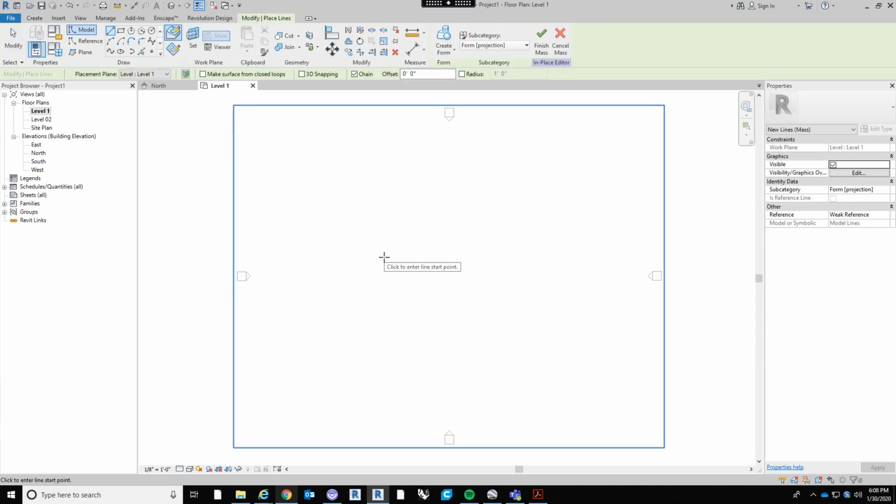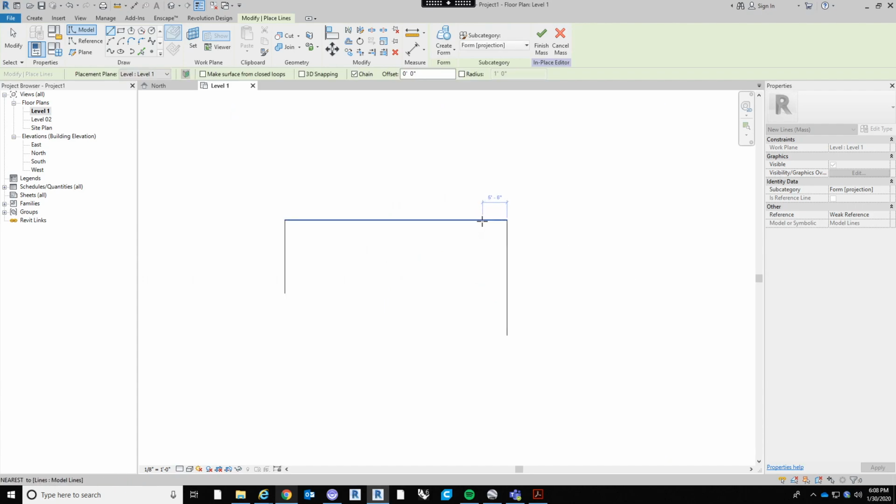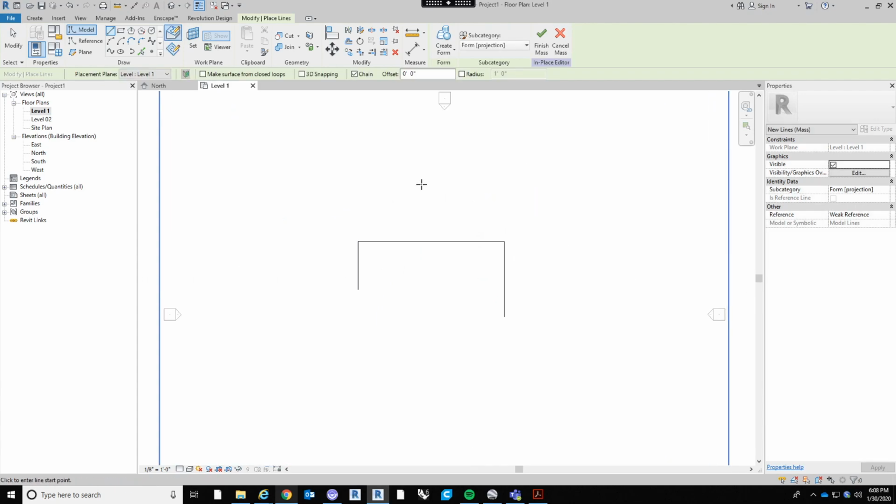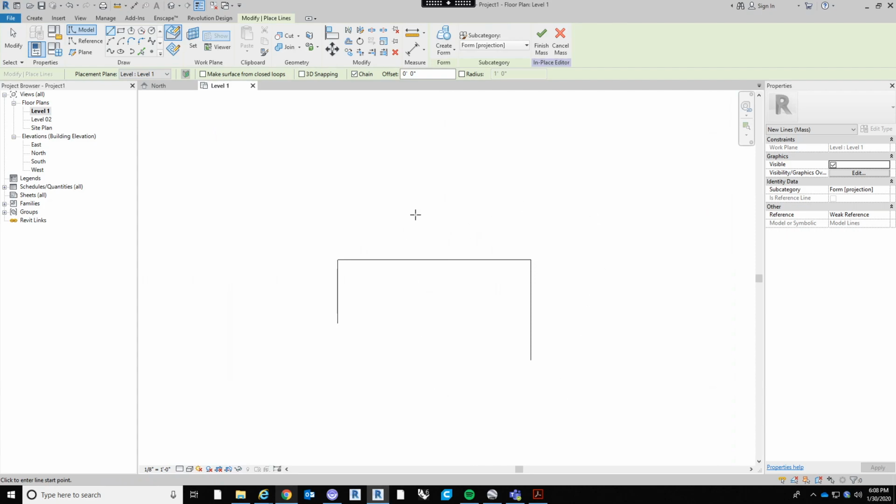It's okay. All right. And then draw 3 straight lines. It doesn't matter what the distances are between them. The 4th line will be a spline. You can either do a spline or spline through points, either way. One is the NURBS-based curve, the other is your exact control points. And then just draw a double curved line.